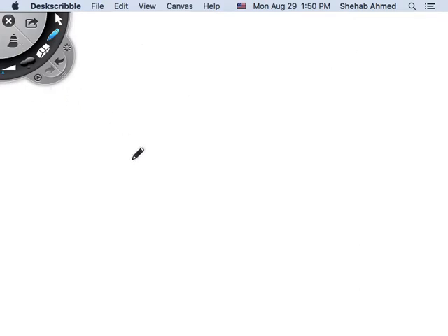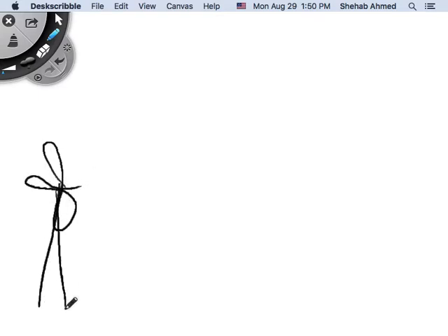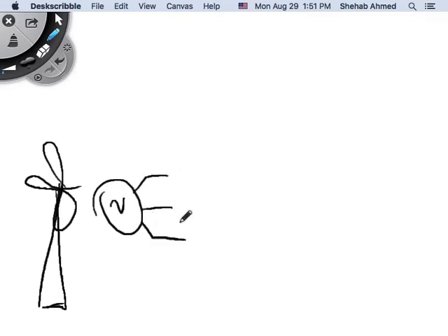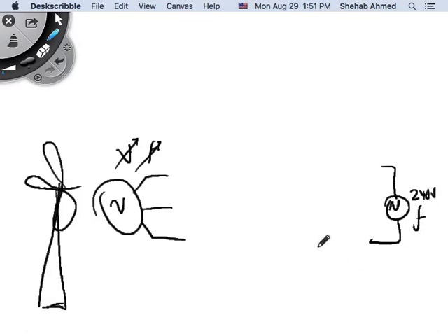How about wind power generation? So this is my wind turbine. It's a three-phase motor, a typical three-phase generator that produces variable voltage and variable frequency depending on wind speed, right? And then, let's say you want to connect this to a single-phase grid. That's 240 volts, fixed voltage and fixed frequency. So what do you do in that case?